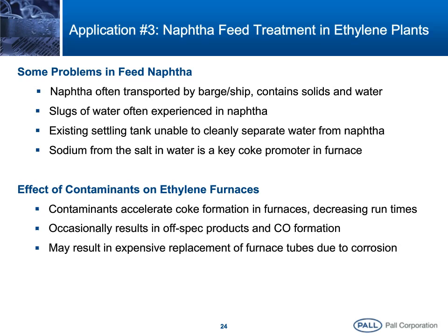It can cause rapid decoking and therefore destroys the efficiency of the furnace. Also, it can form incomplete combustion products such as carbon monoxide and off-spec ethylene. Finally, it may result in so much corrosion that you may have to replace the furnace tubes in the radiation section.